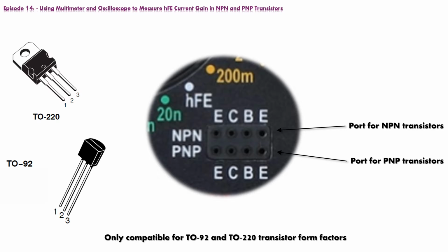It is also important to mention that the hFE port, for this particular type of multimeter, is compatible with TO92 and TO220 transistor form factors. Please consult the datasheet for your particular type of transistor to learn the layout of the terminals.